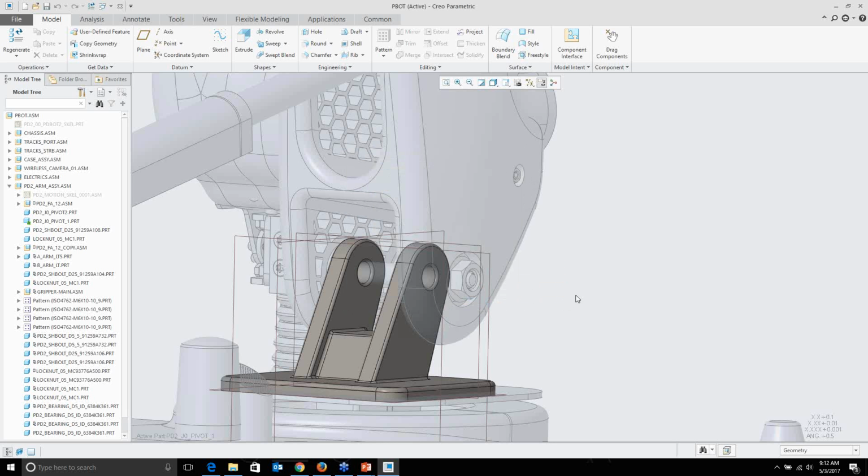Now, how do you go ahead and work around that? I just go ahead and use another letter that isn't a keyboard shortcut. So, for example, Z that I know of is not a keyboard shortcut. So instead of having my map key just be SM, I could just call that ZSM, right? And that will work just fine and do everything I want it to do. So yeah, that's the one thing in Creo 4 that could interfere with how you use the rest of your map keys.